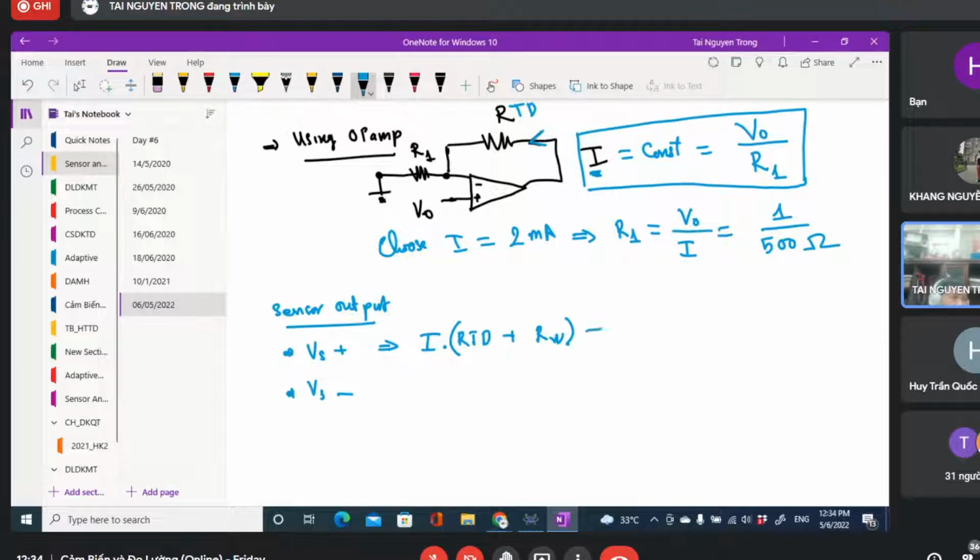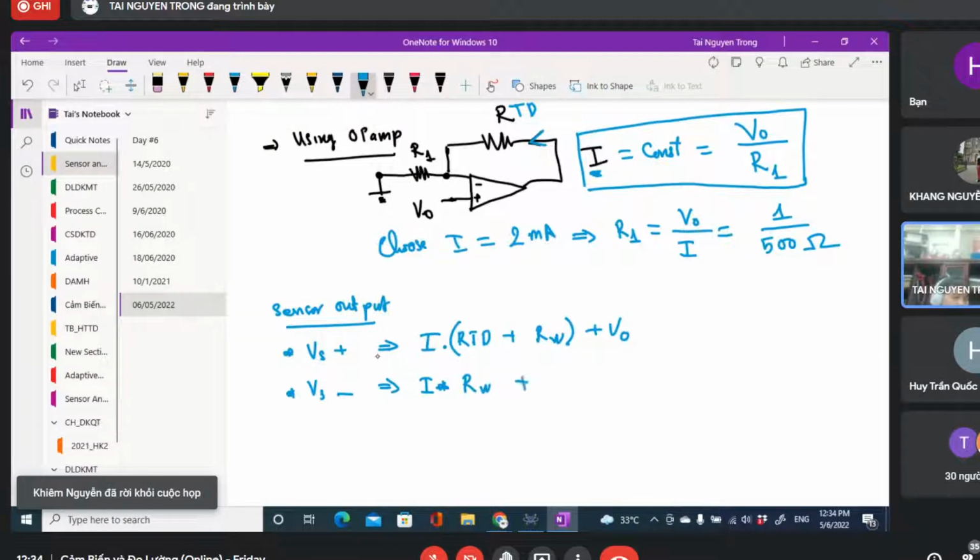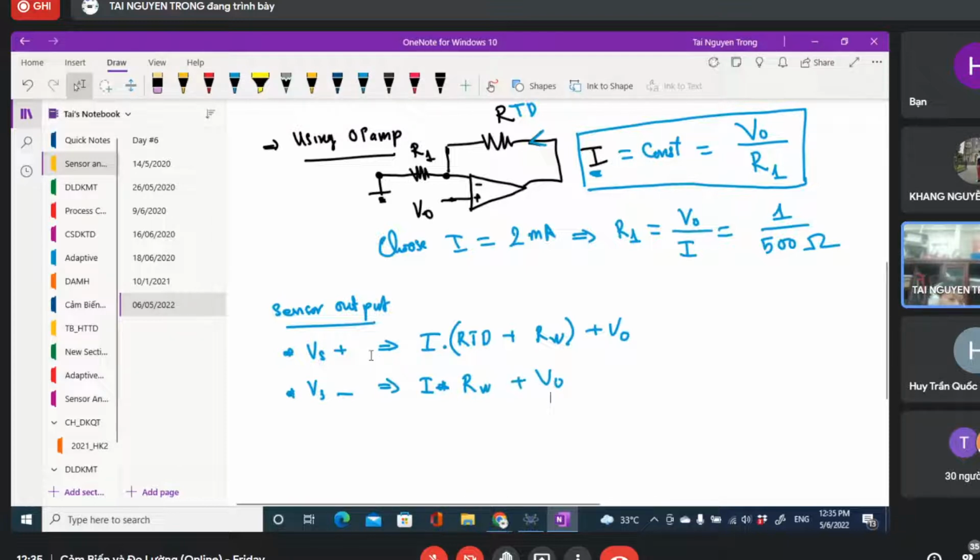Then we determine the necessary phase lead angle we want to add to our system based on that. This is the requirement, this is the current value, and this is some value for the threshold. So we get this, and we compute alpha using this formula and determine the new crossover frequency using this condition.